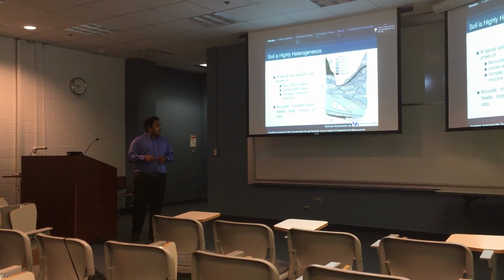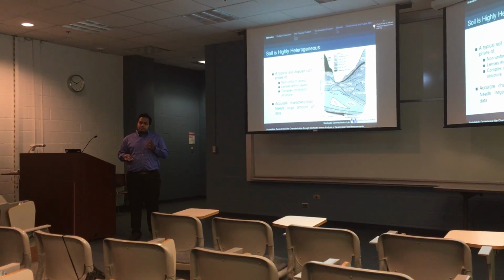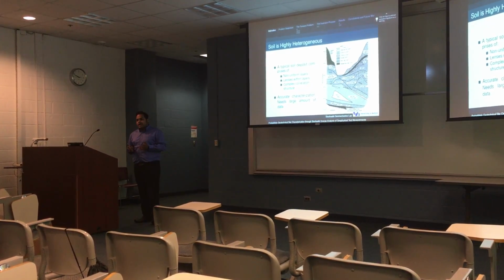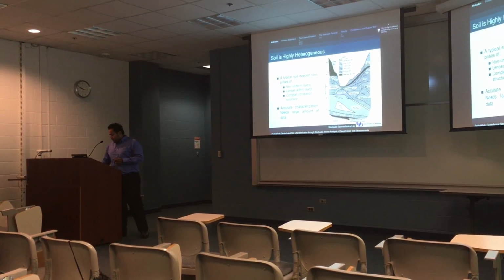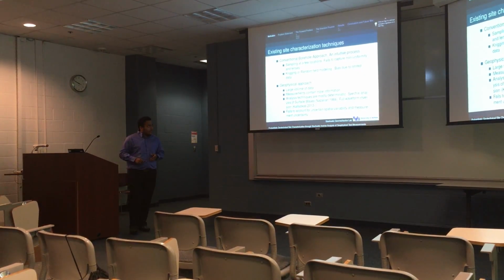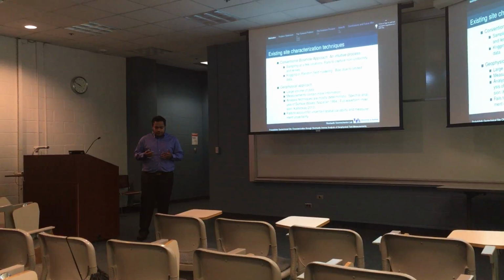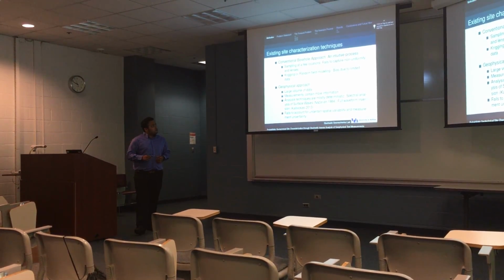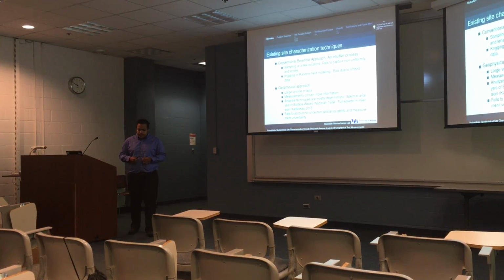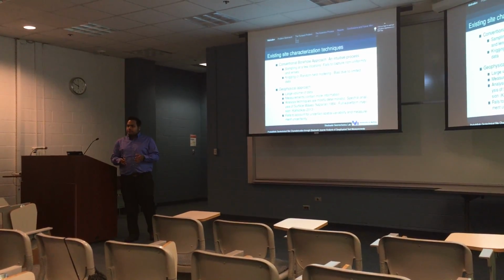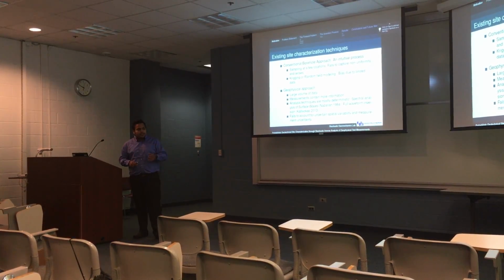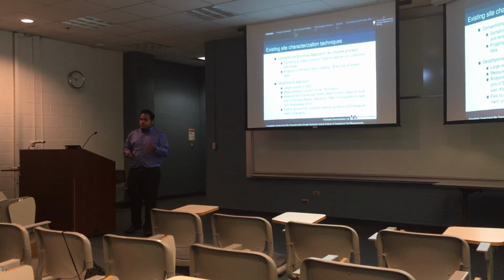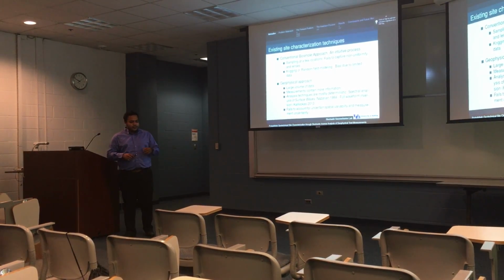But for accurate characterization of this, whether deterministically or probabilistically, we need a very large amount of data. But with the existing site characterization techniques, the data that we get is not always enough. Why? Because we have a conventional borehole approach where we go to the site, we dig holes, collect samples, do some laboratory tests, or maybe some in situ tests.